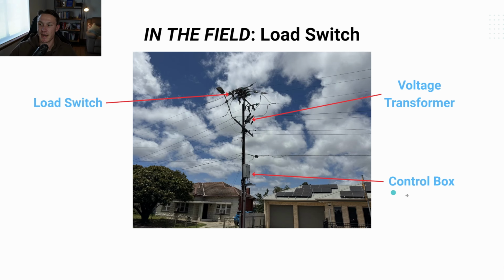Pointing that out here is good for the control box. We've then got the load switch. It looks like a bit of a spider thing that sits on top of the power pole. Internally, when it's operated, it'll actually open and the 2 connections will pull apart. For this to work effectively, it requires a voltage reference provided by this voltage transformer. Similarly to the transformer setup, these have also got isolators to allow simple maintenance. However, I haven't pointed that out because we've seen that already.